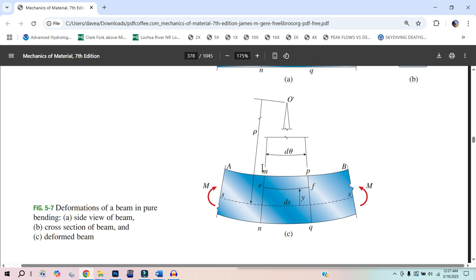And if y was the radius, if you got all the way to the center point, wouldn't your length of this be 0? Theoretically, that's not going to happen. But this would be the original length, and the length would go to 0. Your change in length would be length final, 0, minus length initial. So you'd have a negative original length. The strain equation is change in length divided by original length. And so your strain is just 1, but it's negative 1.